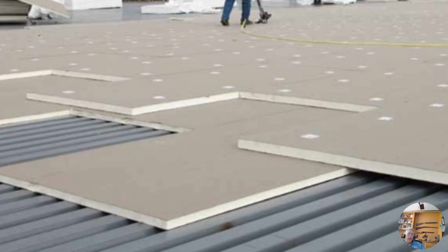This is a picture of a car dealership we did. We did some draw inspections, and if you're from the area, this dealership was on Hall Road in Macomb County. You can see the sheathing is corrugated metal, and then there's 2 layers of rigid insulation over top of that. They connect it down with big metal screws that go into that sheathing, and they've got a big washer on them too to hold the insulation down.